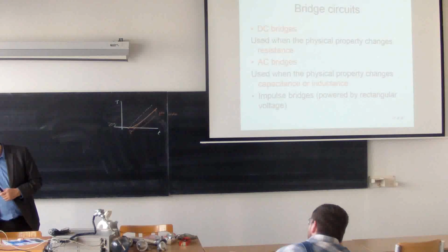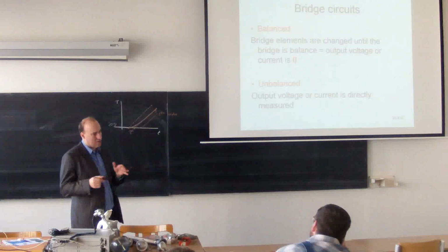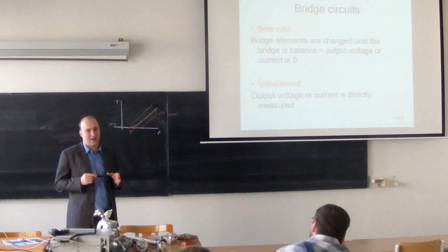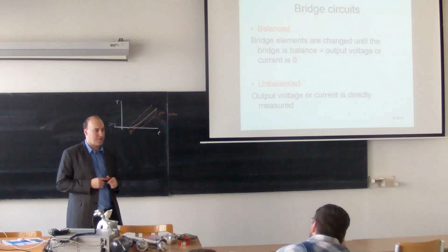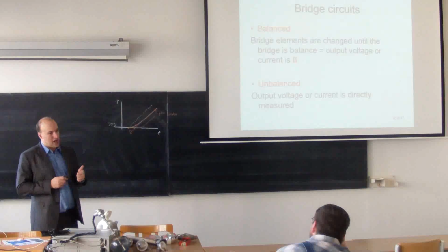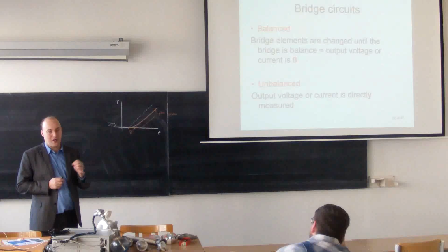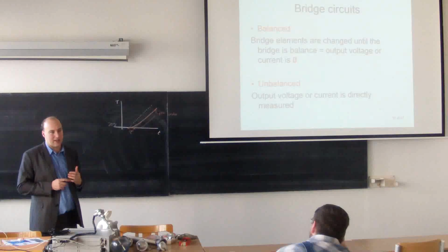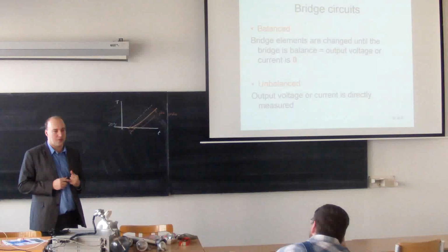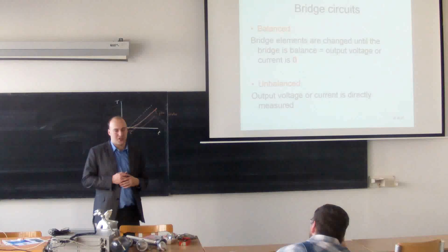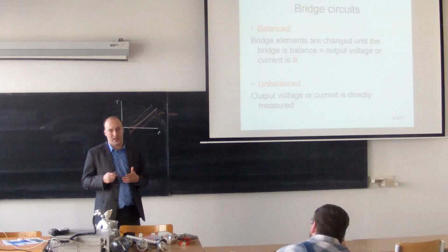There is a second way to look at the bridge. I can take a look at the output of the bridge and at the way I change the setting of the bridge. I can change the values in the bridge and keep changing until I detect zero voltage or current on the output. So I'm looking for some setting of the bridge, and I'm changing it until I have zero.